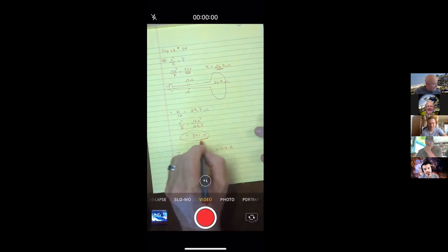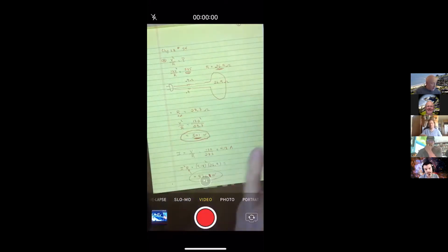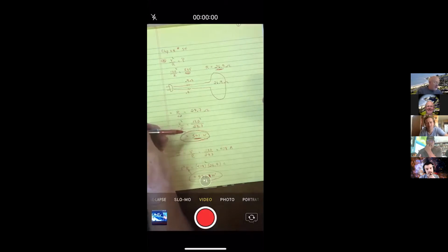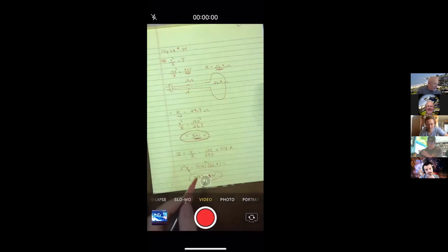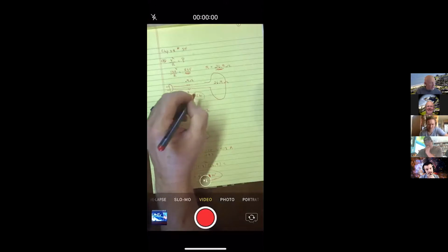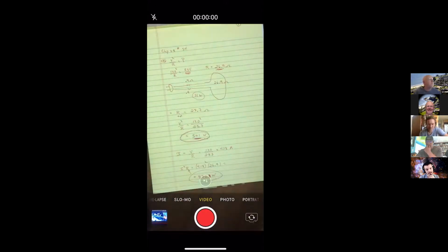Sorry, I didn't read the question well. This is the power total delivered. And so the heating of the extension cord and the running of the vacuum cleaner is 501. So it looks like there would be 31 watts of heating for the extension cord. Okay, so now I can finally get to your main question, which was B. It says if instead the power is to be at least 525 watts, what must be the diameter of each of the two identical copper conductors in the cord that he needs to buy?